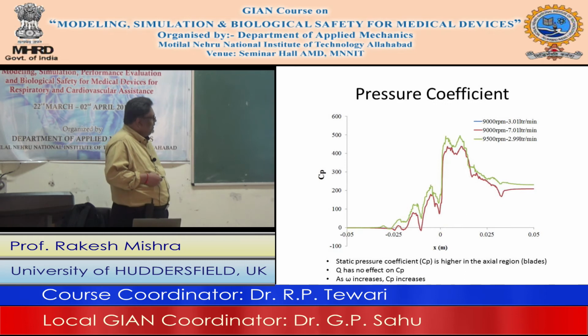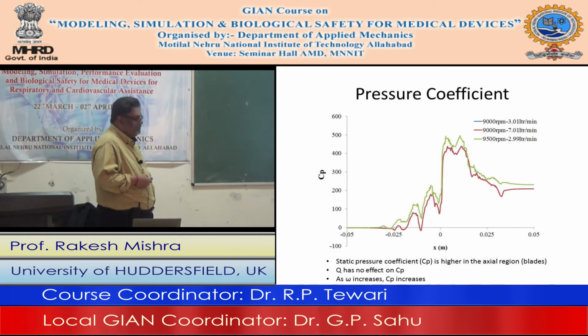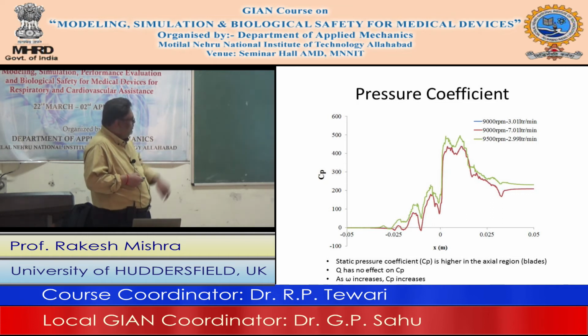So here, this is the straight line part. This is your straightener part. You can see, let's take one value, 9000 RPM. At 9000 RPM, pressure starts to rise slightly here because of the helix available at the straightener. Then in the first part, it goes up, goes down, goes up, goes down, goes up to this particular point. So in the impeller part, pressure is rising.